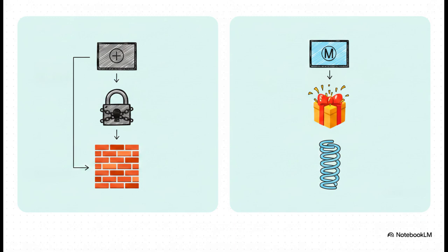The rigid frame means you get exactly 0.25 millimeters of position tolerance no matter what. But the frame with the MMC modifier, that gives the machinist flexibility. It fundamentally changes how you fixture and inspect the part. It's one of those rare times an engineer actually makes a machinist's life easier.